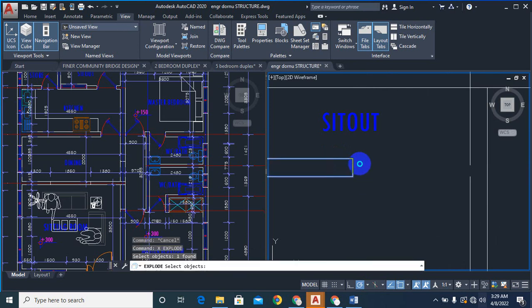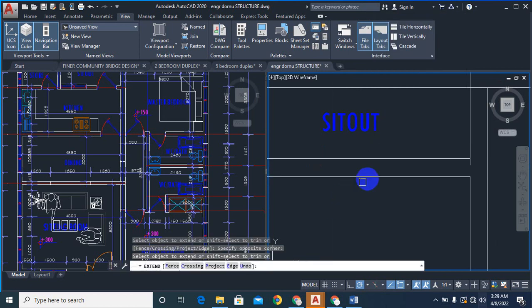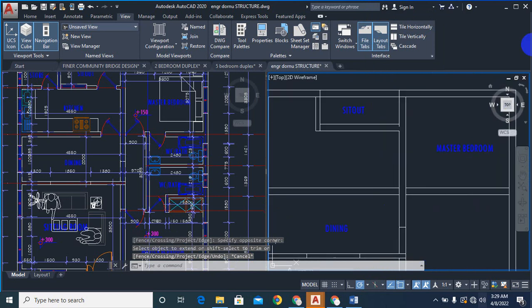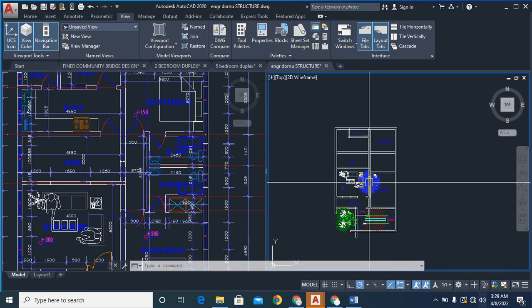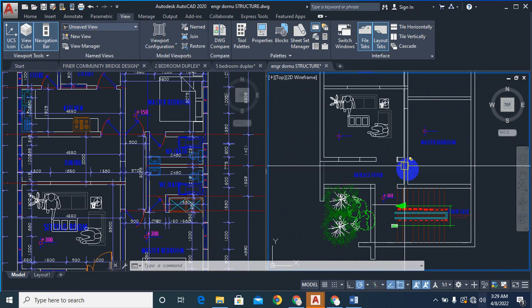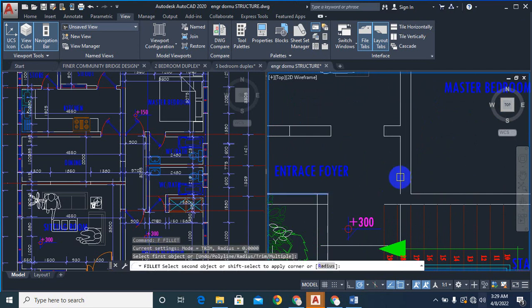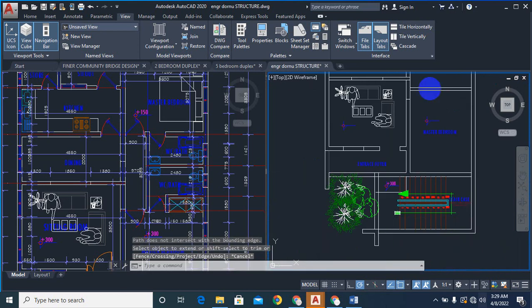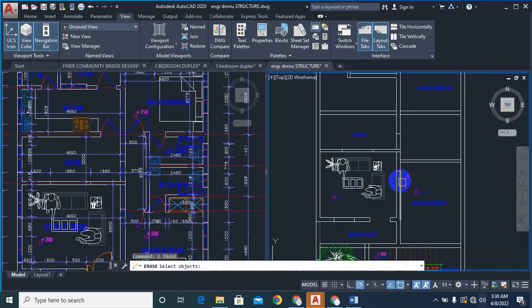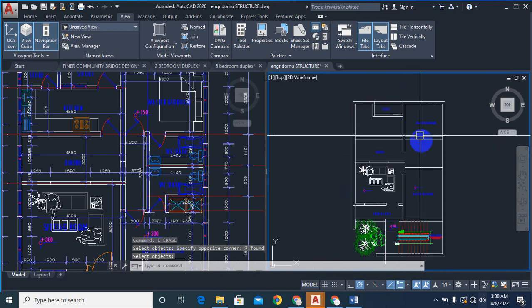Like I said, two engineers cannot have the same general arrangement on one architectural drawing. It's not possible. Both designs can be safe, but one is definitely going to be more economical than the other. There are basic things you need to put in order when coming up with your general arrangement. This design on the ground floor is actually the same as what we have on the first floor, so that makes our general arrangement much easier to come up with.